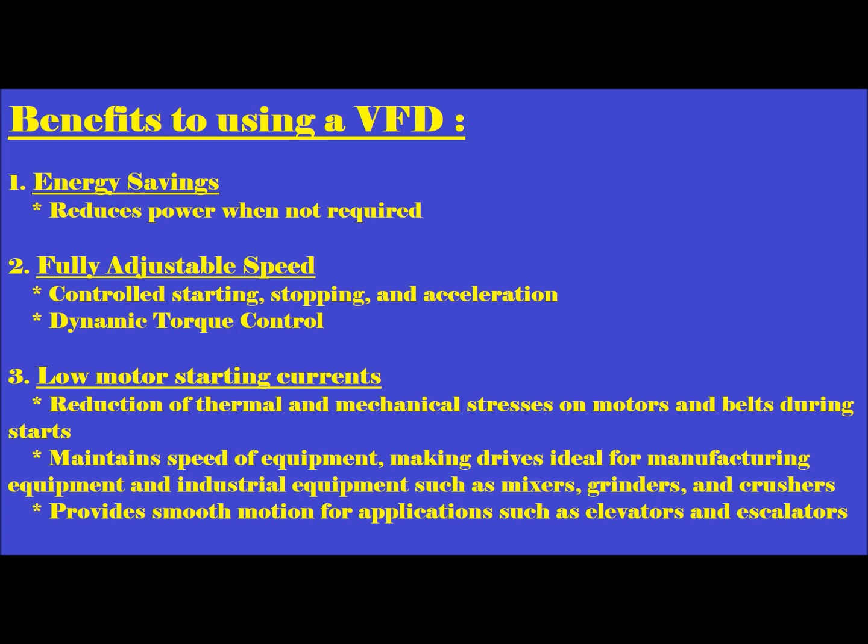The second point is fully adjustable speed. That means it provides control of starting, stopping and acceleration. You have heard the term DTC control, that is direct torque control. This is provided by VFD only. And the third point is low motor starting current, which helps in reduction of thermal and mechanical stress on equipment.